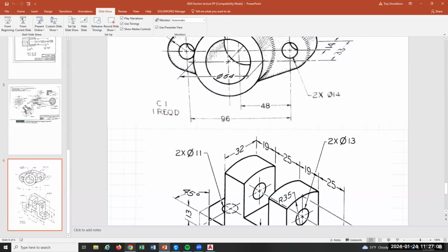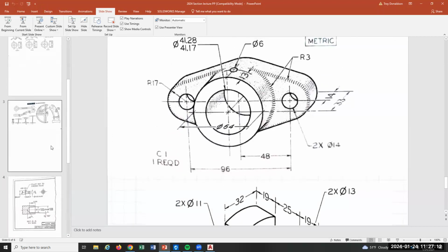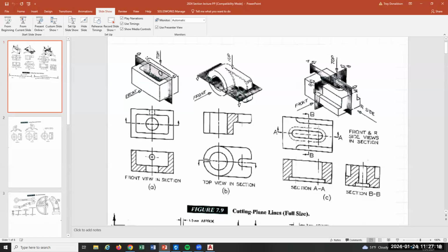So when we mark where it cuts, what do those arrows represent? The cut, the knife that goes down and through. Okay, so like which direction it's cutting? Yeah, see the arrows? The arrows represent which side you're viewing. For example, it's looking this way, that hole better show up. Because if it looked the other way, we wouldn't see the hole, we'd just be looking at this side.